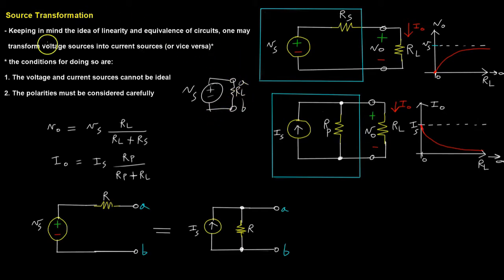But in the real world, your batteries, for example, have internal resistances, internal losses, whether that's from the finite conductivity of the conductor connecting the terminals, or just any other parasitic resistance inside. This could give you a source resistance that is modeled by one single resistor here. And essentially what this is going to do is create a voltage divider between your battery or voltage source and the load. And so what would you expect from that?